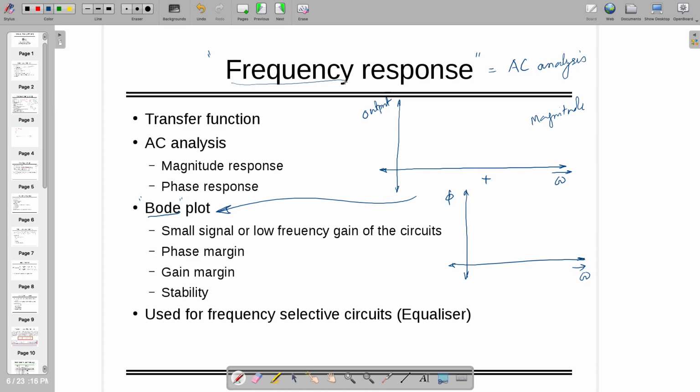3D plot. What 3D plot? We have three different variables. Okay, so in that case, still it's 2D. Generally, we draw like this. Same frequency, and there is magnitude. This is the way to draw. When you use the command like Bode of your transfer function in MATLAB, it is going to give you the combined plot like this.